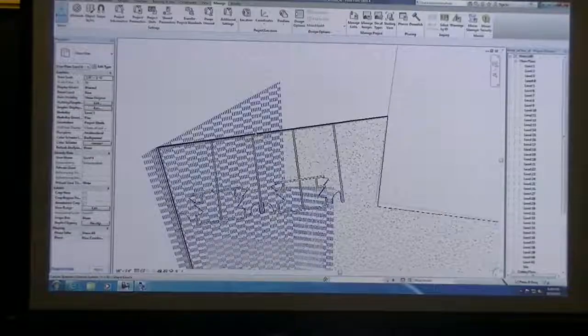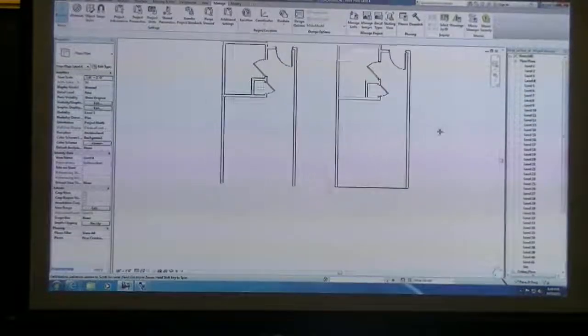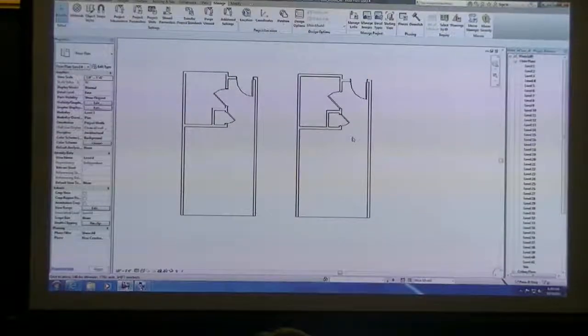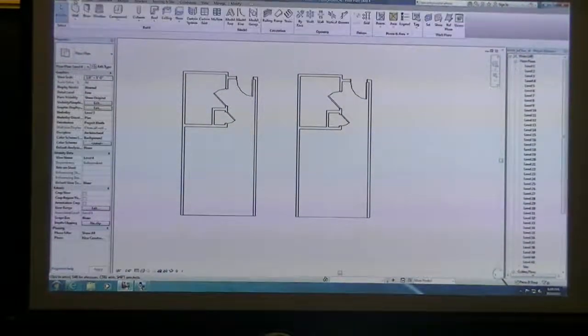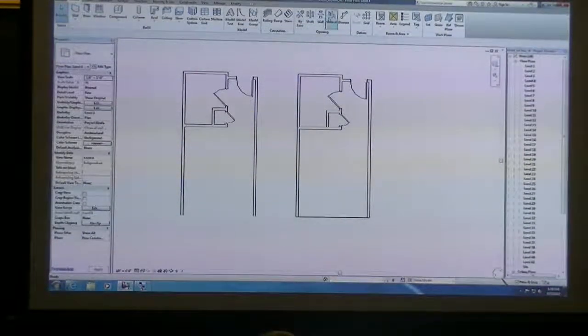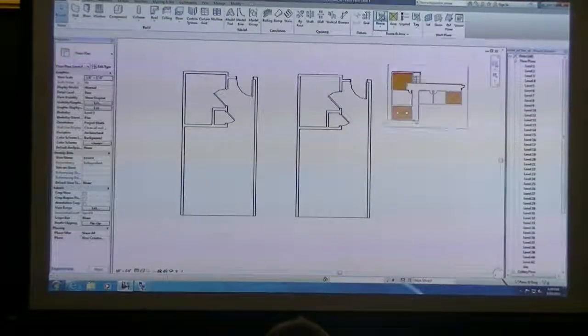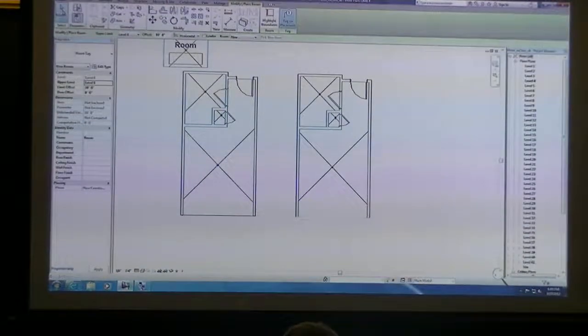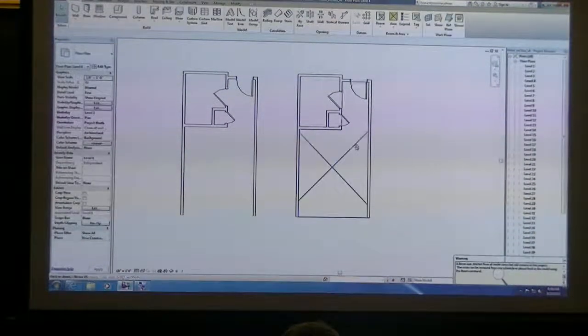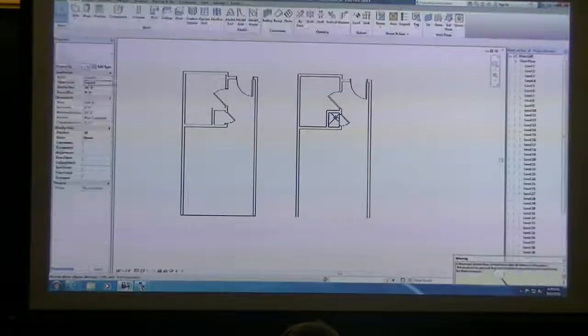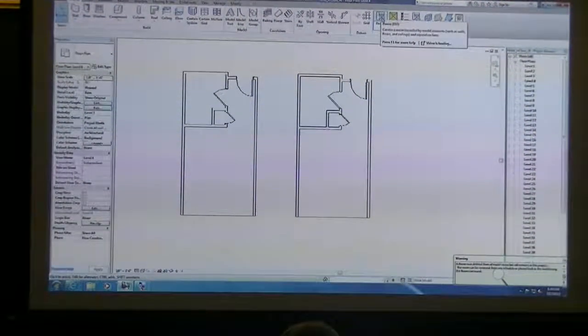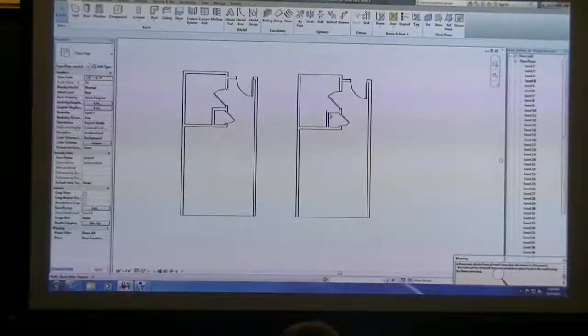I eventually want the exterior wall to finish the shape of my room so that I have views to the outside. When I place rooms within here, I don't know if you've gone through that step yet, because I just told you to do the walls and the doors. If you click on Home and then click on this icon called Rooms, let me delete the rooms that I have in here, the idea is that we are placing spaces, and these spaces are placed whenever you have any kind of enclosed space that has perimeter walls all the way around it.